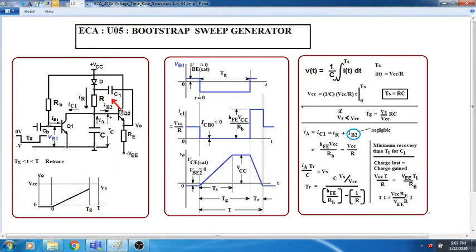Now this capacitor, one end is Vcc, okay, and this end is increasing. So automatically the potential here must be increasing exactly in the way the output voltage is increasing, because this is not connected to any ground. Both ends of the capacitor are floating, in the sense that if this voltage increases, this voltage also has to increase. So initially, before the capacitor started charging, the voltage here was 0, the voltage here was Vcc. Okay, the diode almost has a 0 voltage across it. But once the capacitor starts charging, definitely the diode will go into reverse bias.